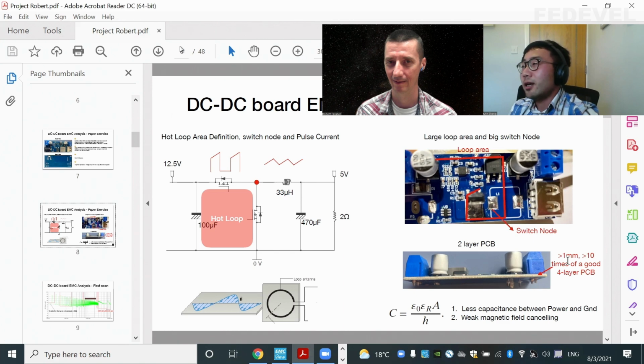Because in this case, the LC is part of the circuit, isn't it? Yeah. But again, for a buck converter, the trick is always on the front end of the design, whereas the boost converter is like a mirror image of the buck. So for boost, the output circuit design is much more important than the input design.